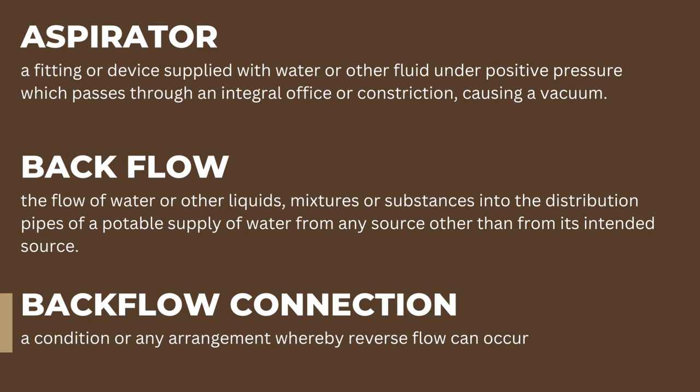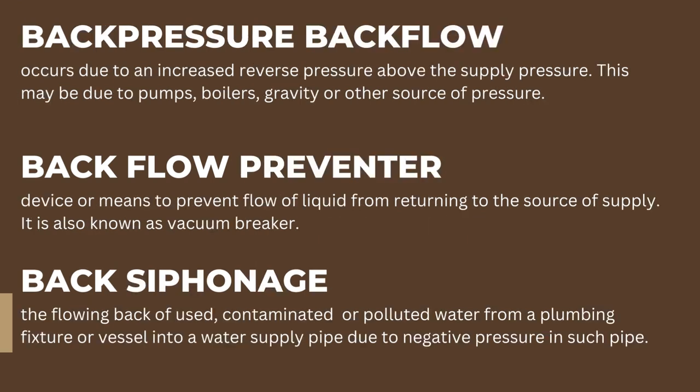Backflow. Backflow connection. It is a condition or any arrangement whereby reverse flow can occur. Backflow connection. Back pressure backflow. It occurs due to an increased reverse pressure above the supply pressure. This may be due to pumps, boilers, gravity or other source of pressure. Back pressure backflow.